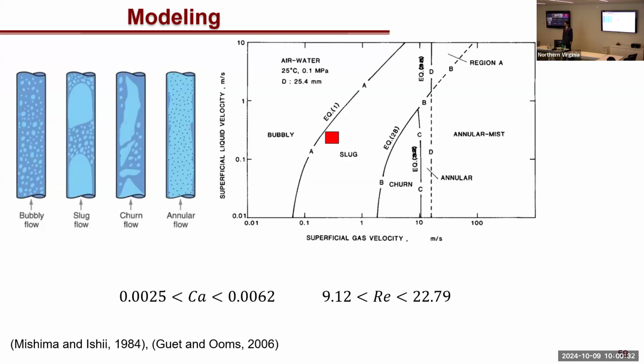But would that be the same case in a molten salt reactor, or would the flow be even faster? How would that affect it? In a molten salt reactor, it's bubbly flow. We're trying to make the flow within our test section look exactly like it would within a molten salt reactor. This microfluidic injector is not actually used for making the bubbles in the reactor. It's used for making the bubbles within our surrogate fluid system. Thank you.